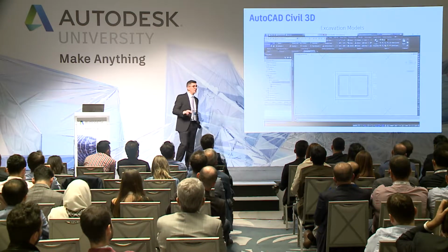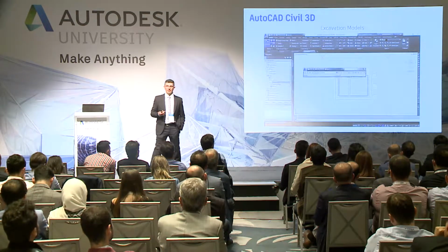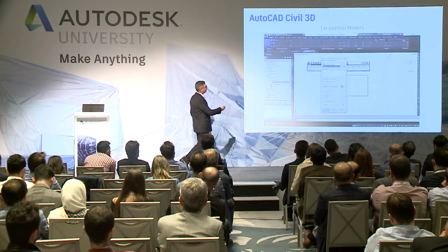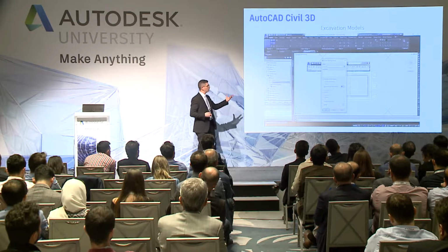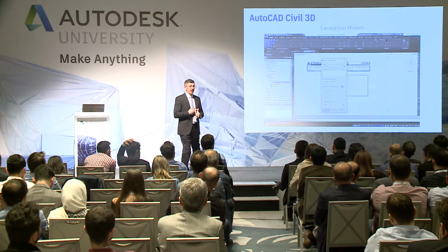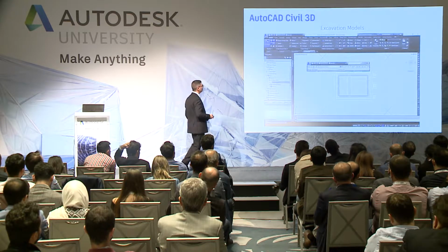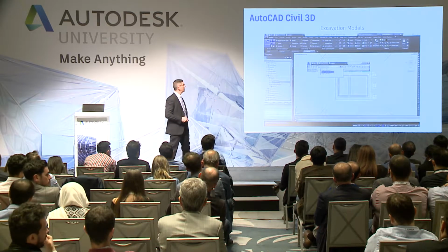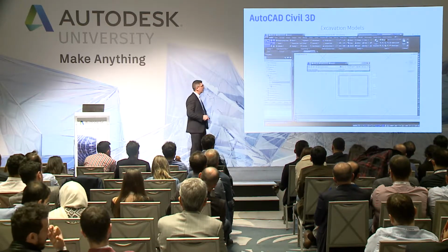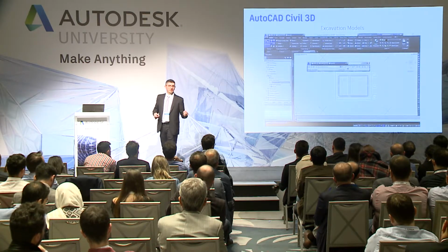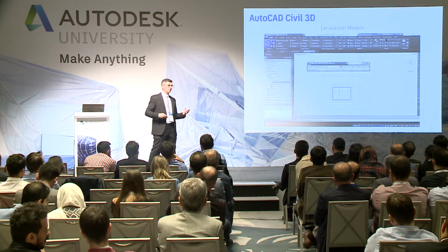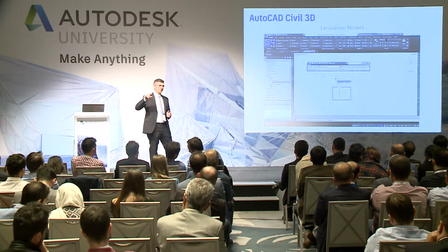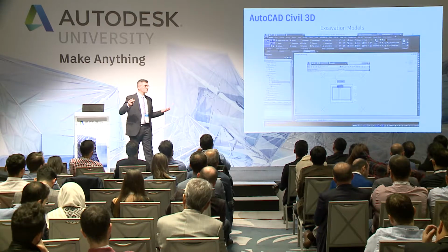I'm starting to create a new object of Civil 3D that is a grading. A grading is the shape of excavation, OK? Again, we have a different window where you need to set the name and the style. The style is the volume. I can select which surface I need to create the interaction, and then I can select the criteria. What is the criteria? The criteria is how you want to excavate or to fill. It's a slope, it's a distance with the slope, it's a distance with delta h, or anything.